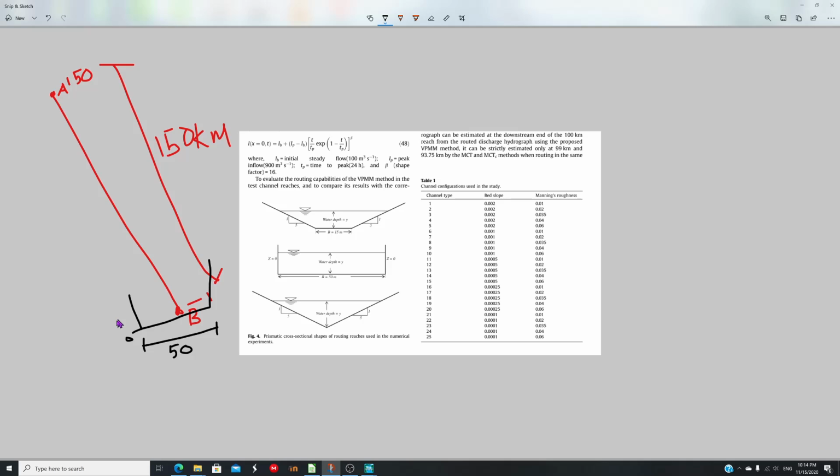Now the coordinates, we also need to supply the coordinates of these points wherever I'm marking. Let me put a new color here, so let's say maybe blue. I need the coordinates of this point. If I take just a reference axis in HEC-RAS, we have to put elevation versus station. The station is the distance from this reference axis. So our cross section is something like this.